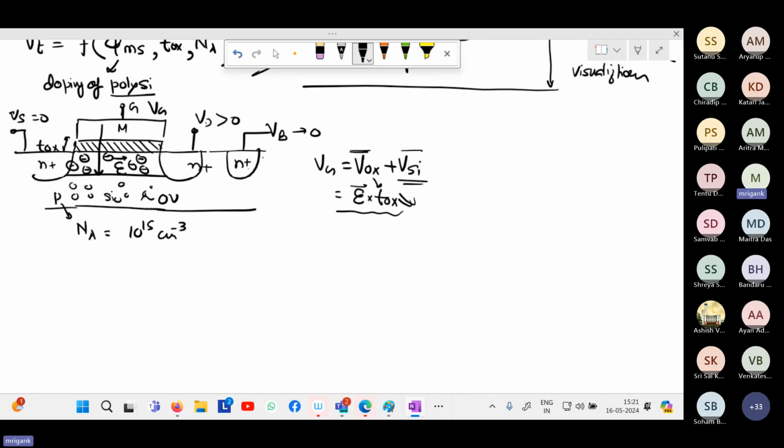Okay, so in simple words, anybody else can explain in simple words? If you have a higher doping concentration in the p-type, since np equals ni squared, that will lower the concentration of the minority charge, that is the electrons. So to form a channel which is able to conduct, we'll need to apply a higher potential, because now the electron density is less in the p-type substrate.